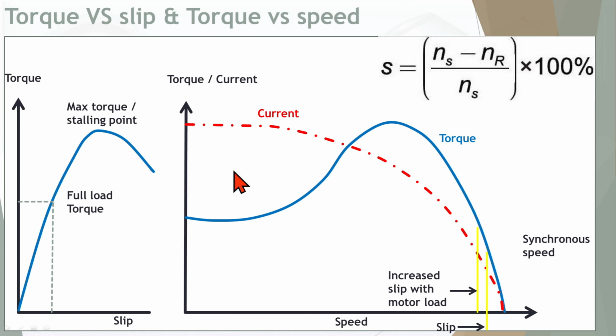Again, an almost similar diagram here, speed versus slip. You can see this is the normal operating slip, this point. Suppose in some case the load torque increases. Suppose when you are filling a tank with a pump, as the head increases, your load will increase gradually. So the load on the rotor will increase, and it will cause slip to increase. So let's say as the load torque increases, your slip increases to this point. Now the operating point will shift to here.